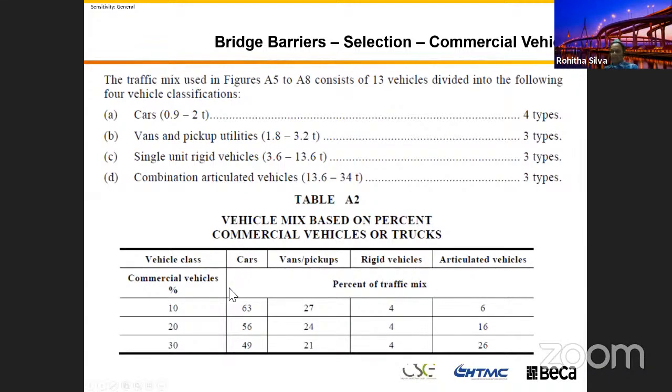If you talk to them, they will give you advice on this particular highway, this particular road composition today, tomorrow, and in 30 years' time. What is the commercial vehicle percentage we expect in our traffic modeling? So please note that you design your bridge for 100 years, so you need to use at least a 30-year prediction in your selection.